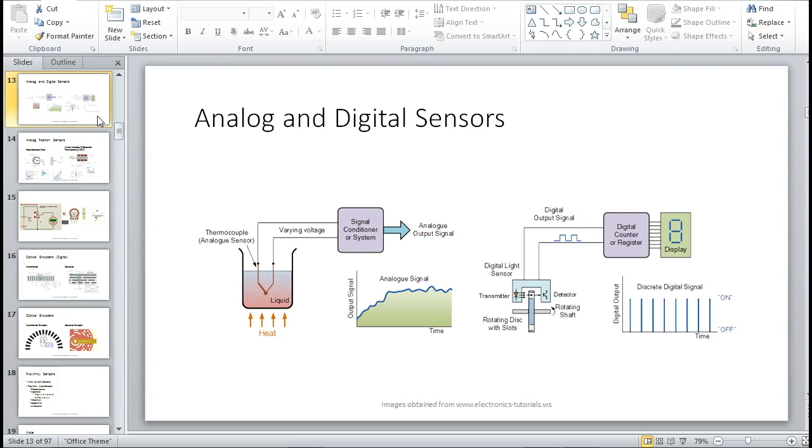Analog would be, okay, what temperature is it outside? You understand? What speed is my car going? So how does my speed control work, so that's a sensor. I'm not doing 90 miles an hour or 0 miles an hour. When I engage my cruise control, that's a closed loop system. That sensor that senses speed, is it analog or digital? It's probably analog. It's probably got a tach generator or something like that, right? You understand?